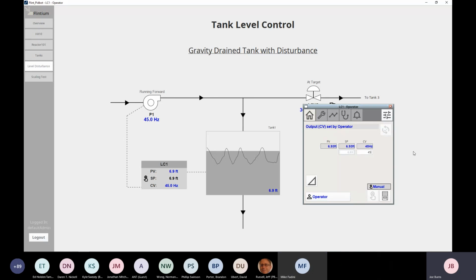Generally, yes. It makes the PID controller non-linear, so it's going to hurt performance to some extent. There are cases where it's going to be useful, but if you can avoid it, just avoid it. I don't have an example where it would be useful off the top of my head right now, but yes, the answer is avoid it if you can.